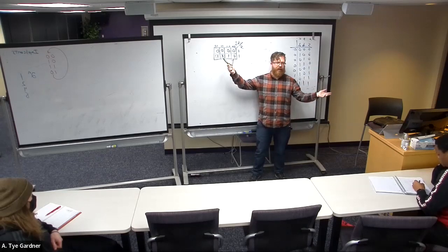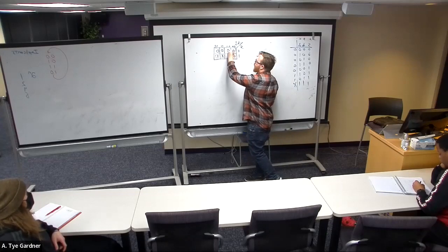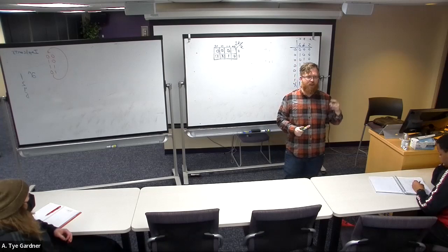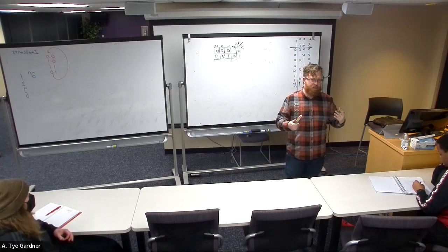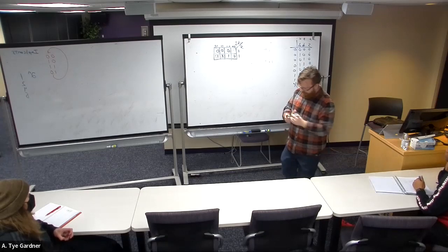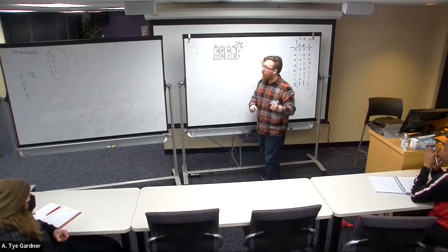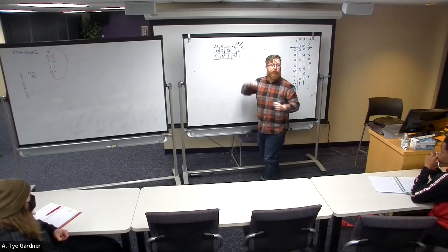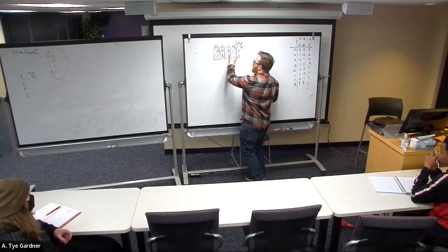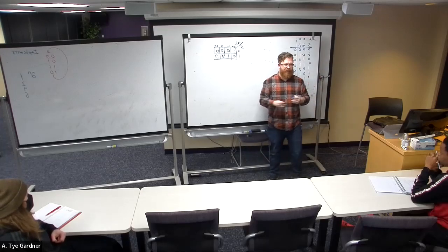That overlap, totally fine. If there was an X up here, I do not have to circle that. X's are not required to complete coverage. Only the ones. But if that X on the bottom was a 1, I can still double up with ones. It's just that the don't cares are extra nice because if it's inconvenient, I can just pretend it's not there.